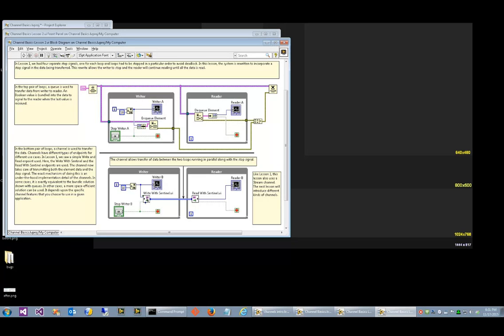Now here's where we start getting even more power behind these channels, and this was really my viewpoint starting to shift. I tried a little experiment on a number of my customers, both internal to NI and external. I took the standard producer-consumer shipping example that Darren wrote, where you hit the stop button and both loops stop immediately. And I said, convert this so that when you hit stop on the producer, the consumer keeps running until the queue is empty, and only then does the consumer stop. So, a nice, gliding to a normal stop sort of effect.